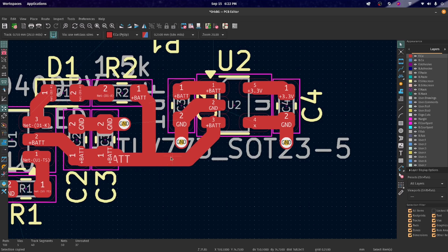I can cut this trace and tie the enable low, or even change where the enable signal goes. But if I routed everything underneath, I wouldn't have access to cut the trace without desoldering the device and making small cuts. Where here, I have a nice area I can cut right here.